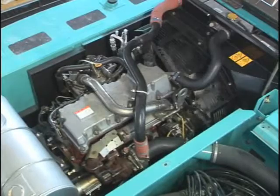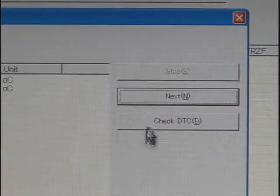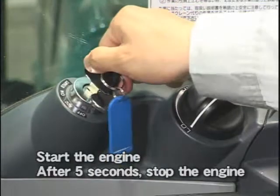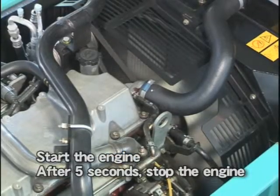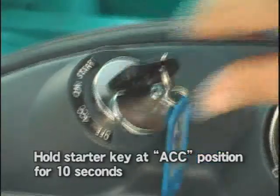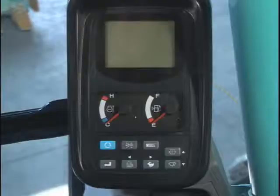Stop the engine. Turn the starter key on. Click Next. Then start the engine. After 5 seconds, stop the engine and turn the starter key ACC. After 10 seconds, with pressing the buzzer stop switch, turn the starter key on.